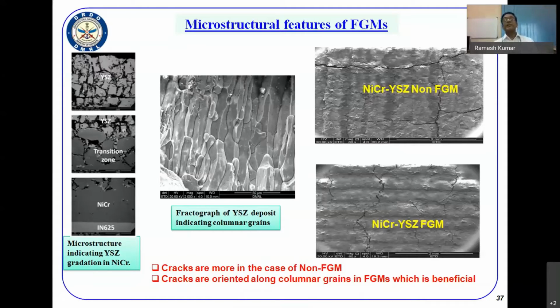This is the sectional layout. Part 2 is welded onto part 1. The center one is the fuel injector, and there will be 2 oxidizer injectors, where combustion will take place. So this is a component which has been considered for development through powder bed fusion technology.